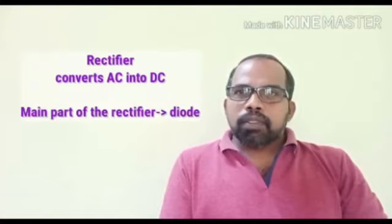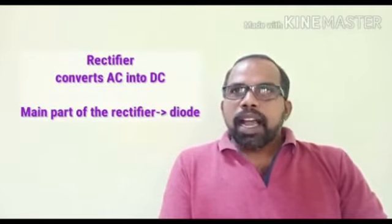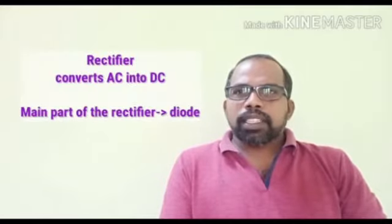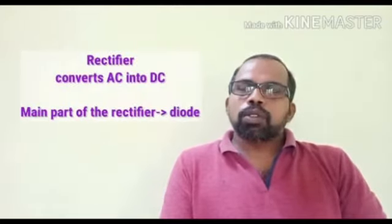A rectifier is a device that converts AC into DC. AC is converted into DC after lowering the 230 volt AC to 12 volt or 6 volt as required for the devices. This is done by using a step down transformer or inductor. The main part of a rectifier is an electronic component named diode. This diode conducts current only in one direction. In addition to such, rectifiers that make use of different electric components are also in practice.